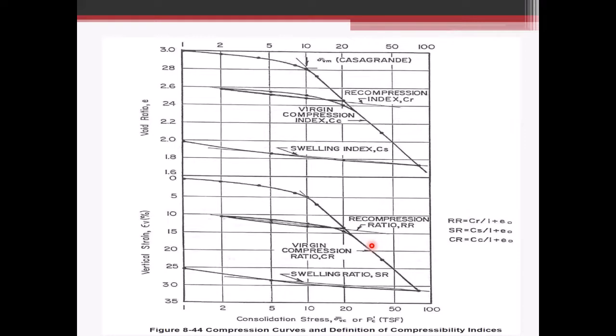And from that data, a consolidation curve is generated. Here's a curve from the Geotechnical Design Manual. One of the important things that geotechnical engineers look at is the preconsolidation pressure of the clay. A lot of clays in New York State, because they've been glaciated, have had a lot of weight over them due to the glaciers, or they've been dried out and desiccated. So they've had a much higher pressure on top of them than they currently see.